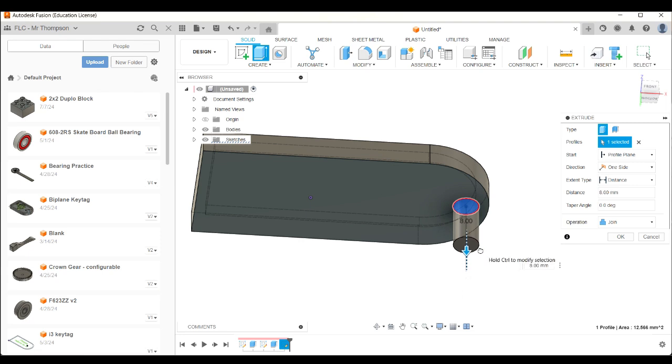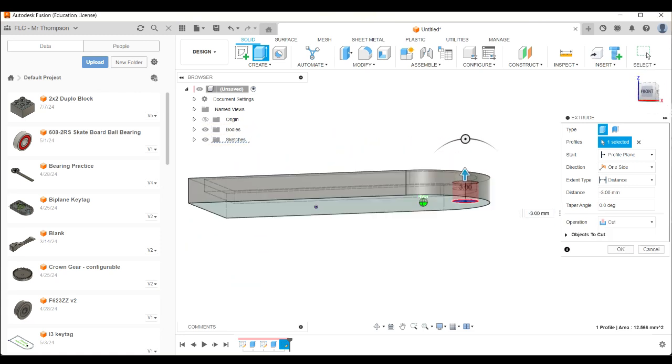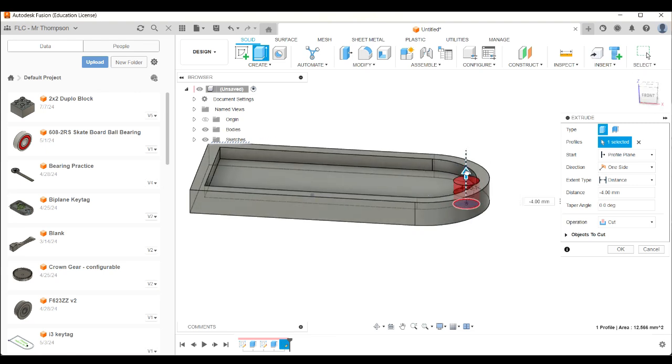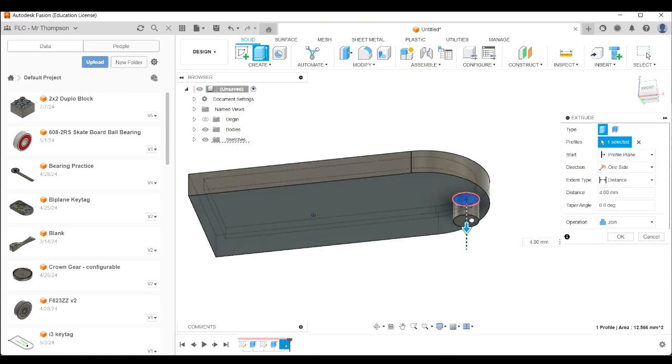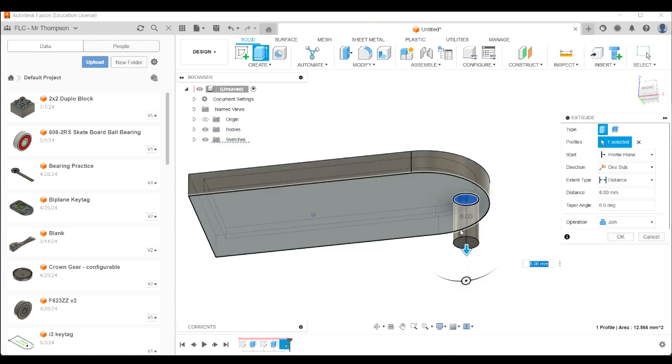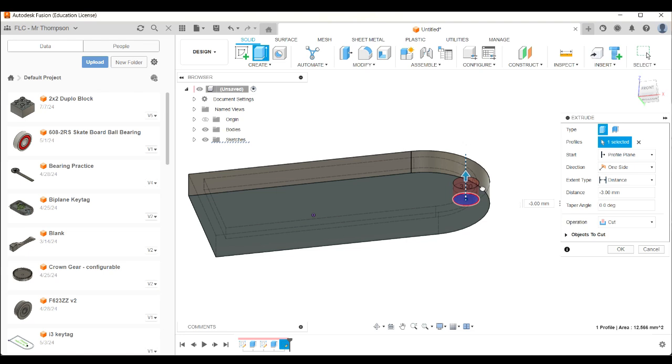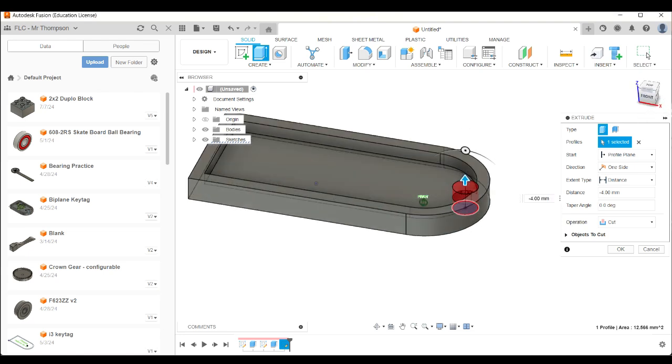I'm going to do a different type of extrude where we're actually doing a cut. So if I push back this way, can you see now it's creating a hole because I'm extruding backwards into the material that's already there. So that's a cut. See down the bottom here how it says cut. So if I come back here, if I'm making more material, that's called a join operation. If I'm coming backwards and I'm cutting away something that I've already built, well, that's a cut extrusion.